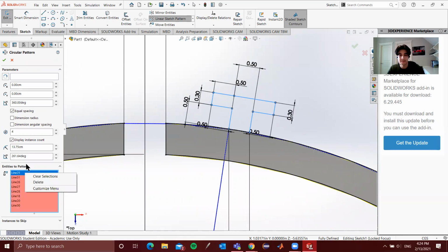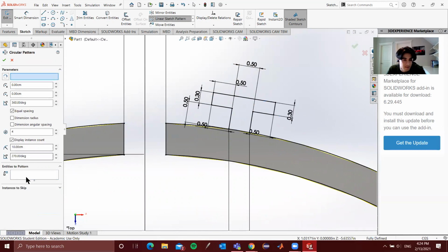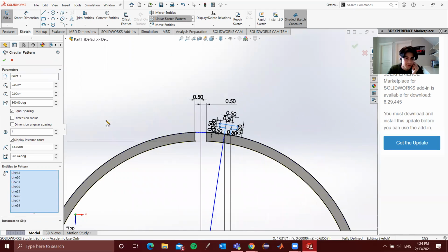And then I'm going to use the circular pattern tool to actually pattern it. Now, for some reason, it's selecting our circle as well, which is not what we want. So I'm going to go back and do what we just did right from the get-go. Okay, I guess it should be fine. No need to worry about it too much. Now, I'm going to establish a certain angle or the space between each of these iterations. So let's say it's around 15 degrees or 30 degrees. Actually, let's say around 40 degrees. Yeah, that's probably best. There we go.